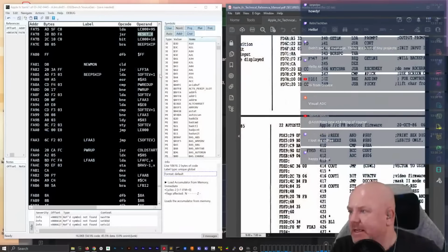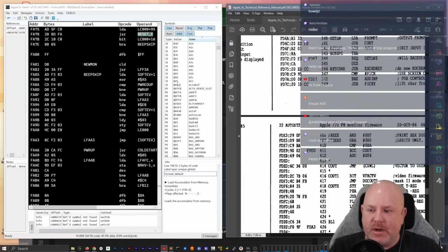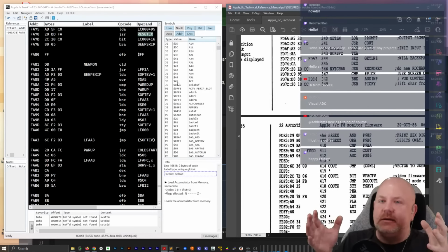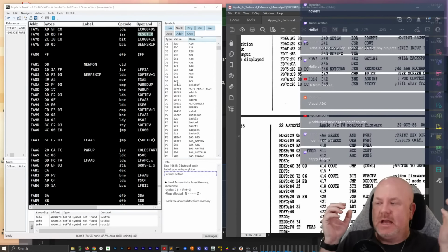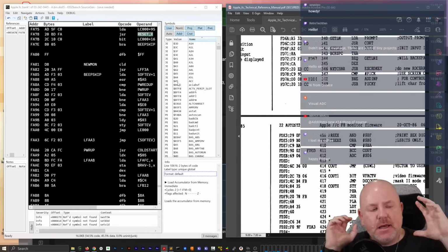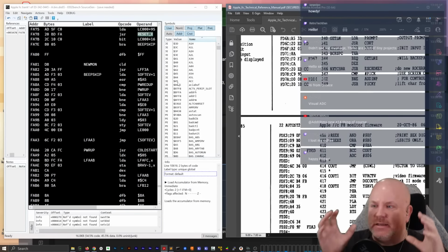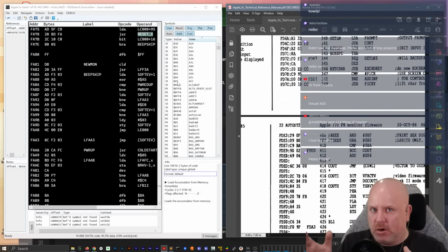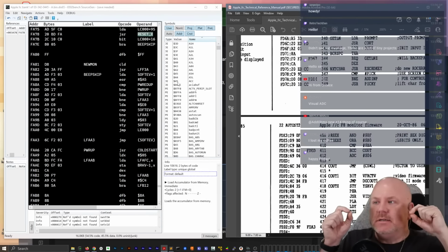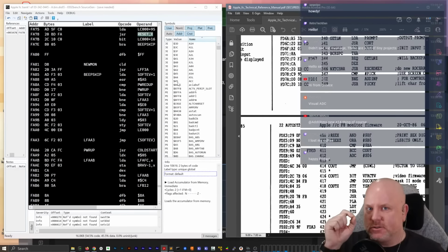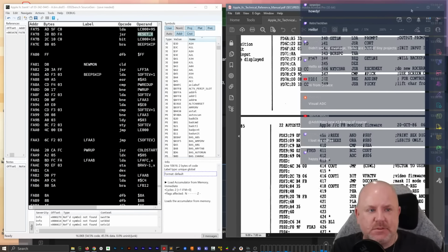With that, I want to get into the project, but first, on the Mega 2E, it has the IWM chip from the Apple IIgs, which was also in the Apple IIc, and by default, that chip acts like an old school Apple II disk card. I've been trying to figure out how to get the ROM from the Apple IIc into the Apple IIe ROM that I'm using, so that I can use that chip to talk to hard drives and 3.5-inch disk drives.